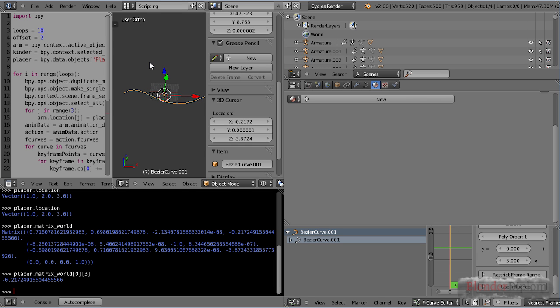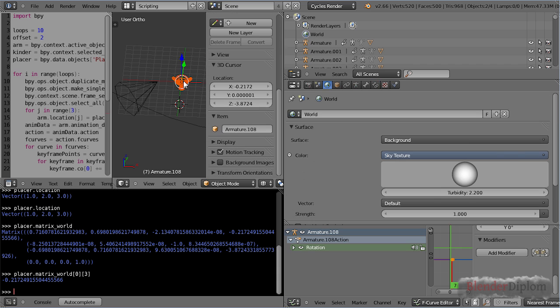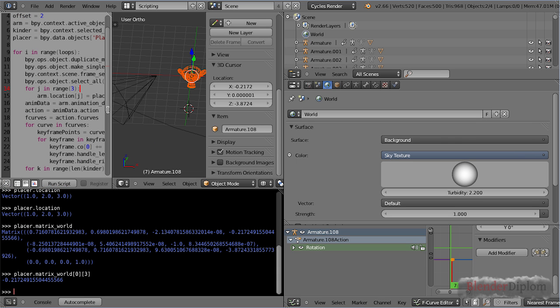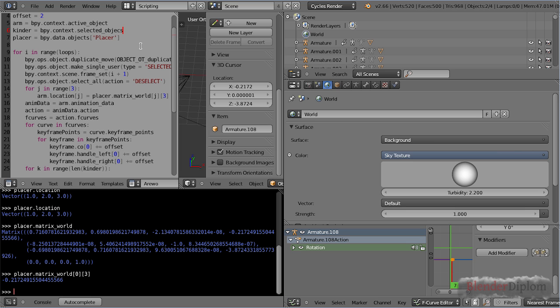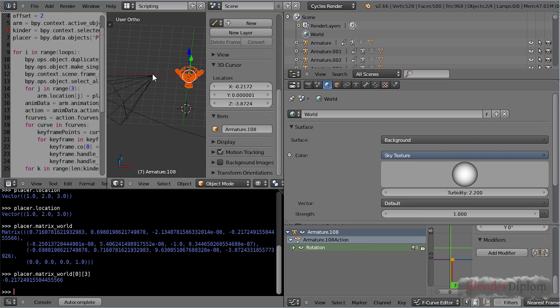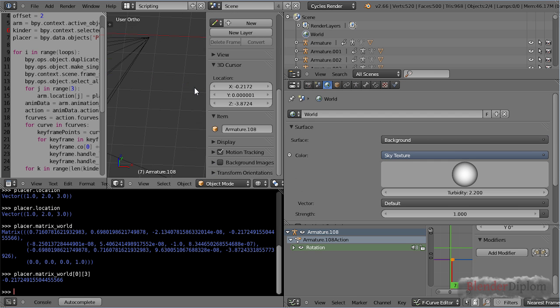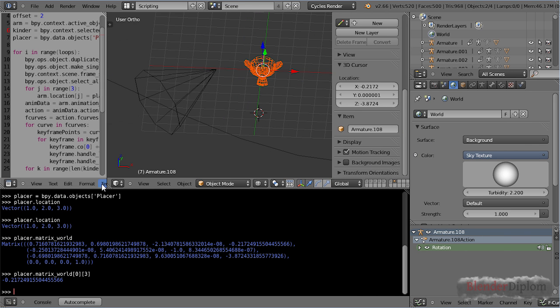And let's test this one more time. Run script. And this is something I really don't like. By pressing undo after running the script, it erased my T that I placed in here again. So be aware of that. Before you press run script, after you change your text, select something. Select something and then maybe reselect or deselect it. This is to make sure that these weird arrows don't happen to you. So again, run script one more time, and that worked.